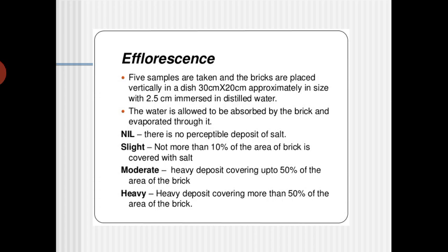Of course, take the bricks randomly, as we have done for the compressive strength and water absorption tests. Then the bricks are placed vertically in a dish approximately 30 centimeter by 20 centimeter in size, with 2.5 centimeter immersed in distilled water.